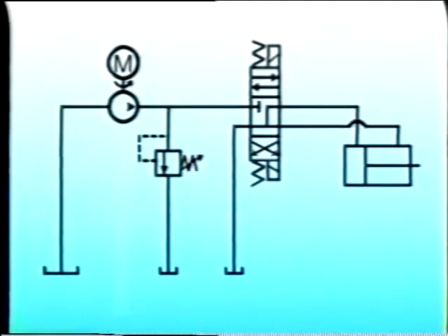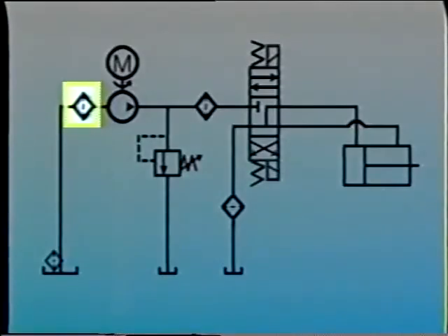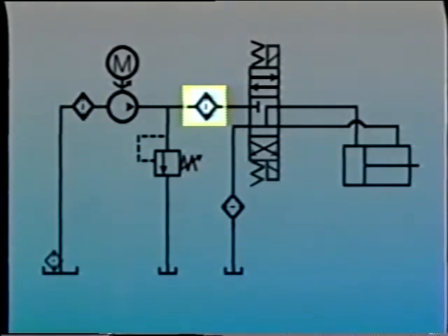Proper maintenance of filters is critical to the operation of the system. As we said, dirty sump strainers can cause pumps to cavitate. As suction, pressure, and return line filters get dirty, the pressure differential between the filter's inlet and outlet gets larger and larger. A very dirty suction filter could cause the pump to cavitate. A pressure filter could rupture or collapse.